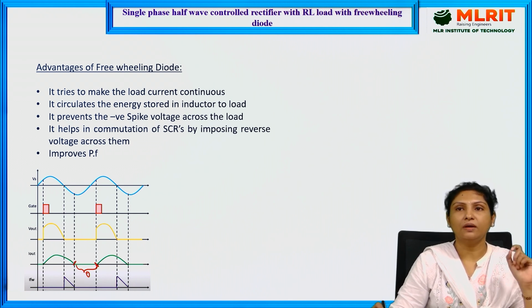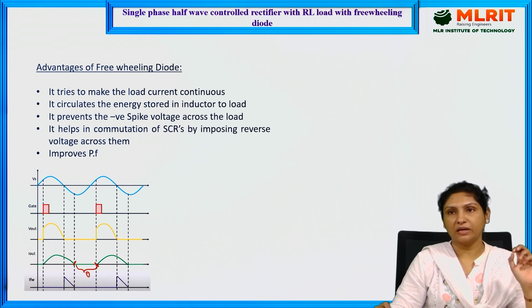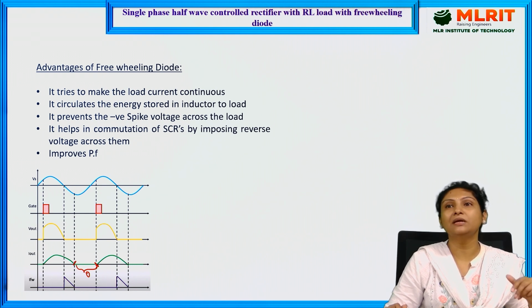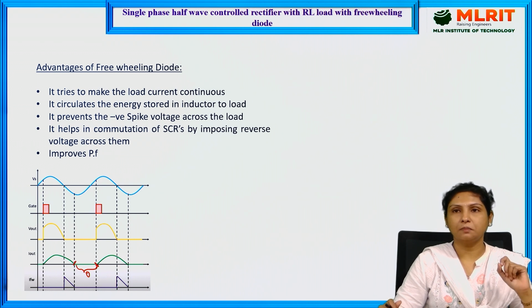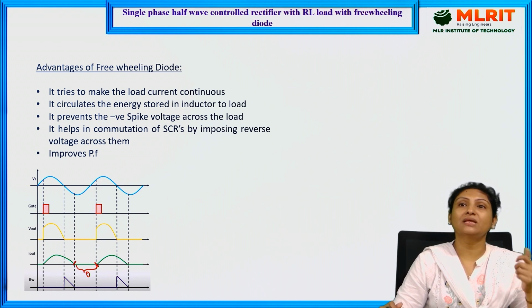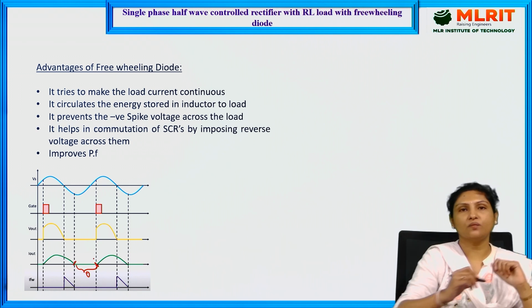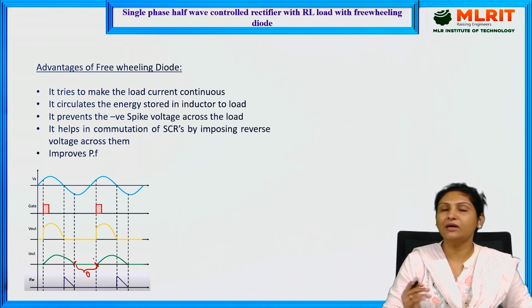During negative half cycle, there is no current which is flowing through the load. If we are making use of this particular single phase half wave rectifier to the DC motor load, in that case, the output current through the motor will be intermittent, which is not desirable. So for that purpose, if we can make use of a very large value of the inductor, the output current through the load will be continuous.